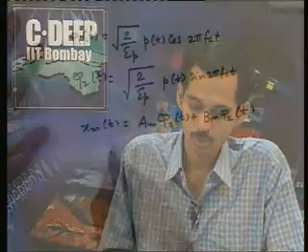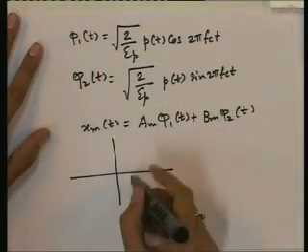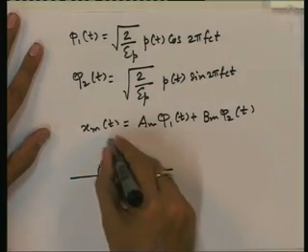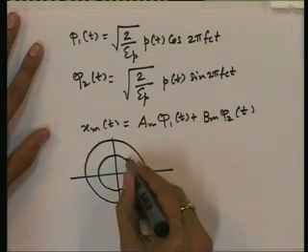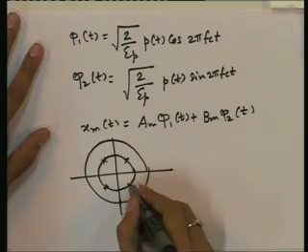So let us see some typical QAM constellations. Suppose we want to have 8 points on the constellation. One way to get 8 points is to take 2 PSK circles, one circle here and another circle here, and then take 4 points on each. It is like a shifted version of 4 PSK.